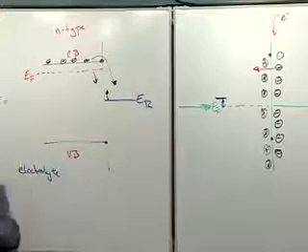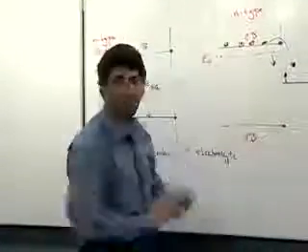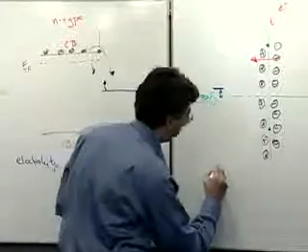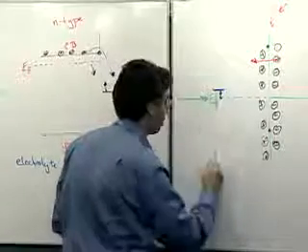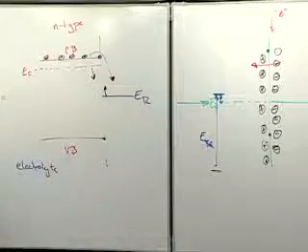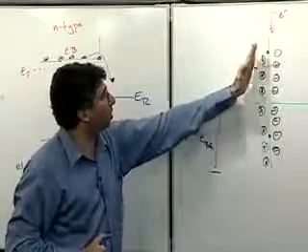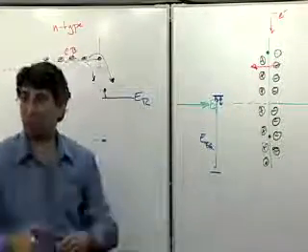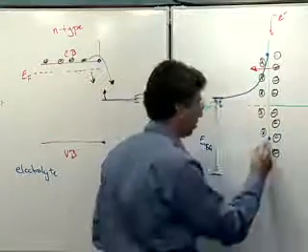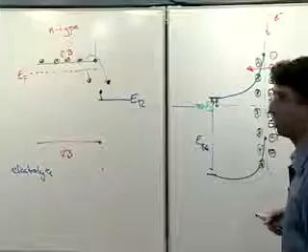Okay. Now, the semiconductor does not change color when I dip it into the electrolyte and it comes into equilibrium, so the band gap has to stay the same. So I take this band gap spacing and I move it over here somewhere, and that hasn't changed. And that can't change anywhere. Okay, but at the surface, I have set these potentials, and I have imposed an electric field at the surface, which is going to change the energy of the surface. So I connect everything together so that the band gap stays constant everywhere. And I have this band bending.